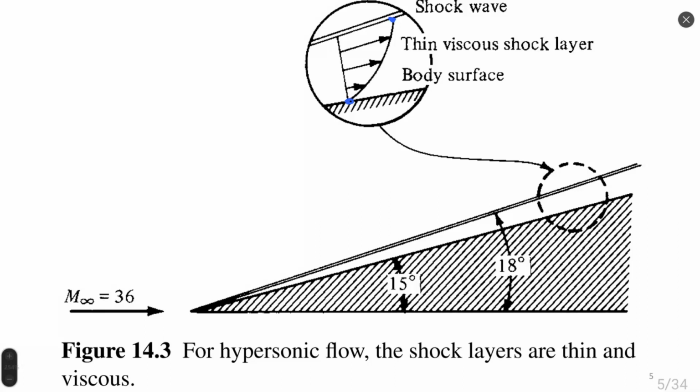does not leave space for smooth flow transition. Flow is quite rapidly changing, and practically all the space between the shock wave and the body is occupied by a boundary layer. This is the so-called shock layer. A shock layer is a combination of a boundary layer and a shock wave.